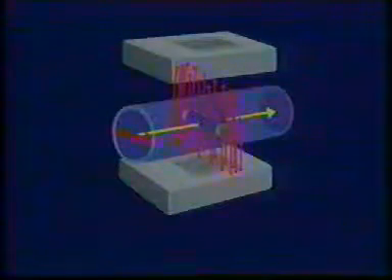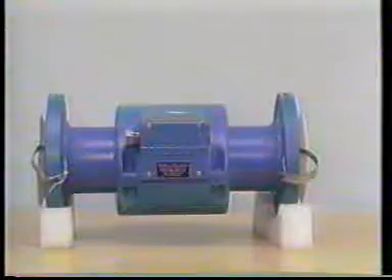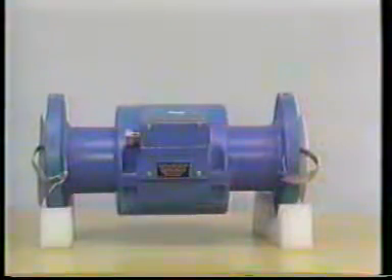With a magnetic flow meter, the flowing process fluid serves as the conductor. Thus, the millivolt output of the flow meter is linearly related to the velocity of the flowing process fluid. The flow meter itself consists of a straight length of pipe with no obstruction, so it does not create any additional pressure drop in the pipe.